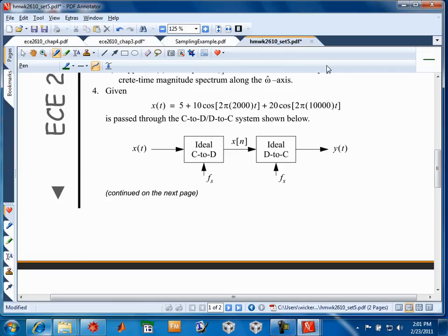A Fourier series, remember, only works for periodic waveforms, so the spectrum is always going to have spectral lines in it that are harmonically related. Whereas the line spectrum, when it was first introduced at the start of Chapter 3, there was no notion that the spectral lines had to be harmonically related. That wasn't a requirement. But in a Fourier series context, everything has to have a root frequency or fundamental frequency that it's based upon.